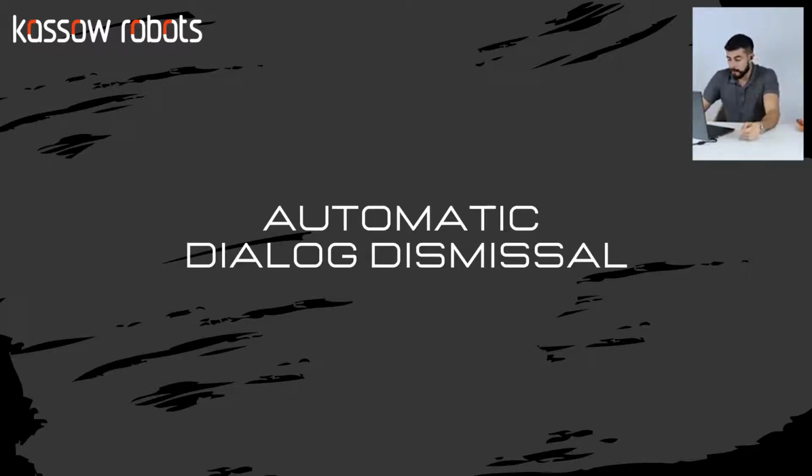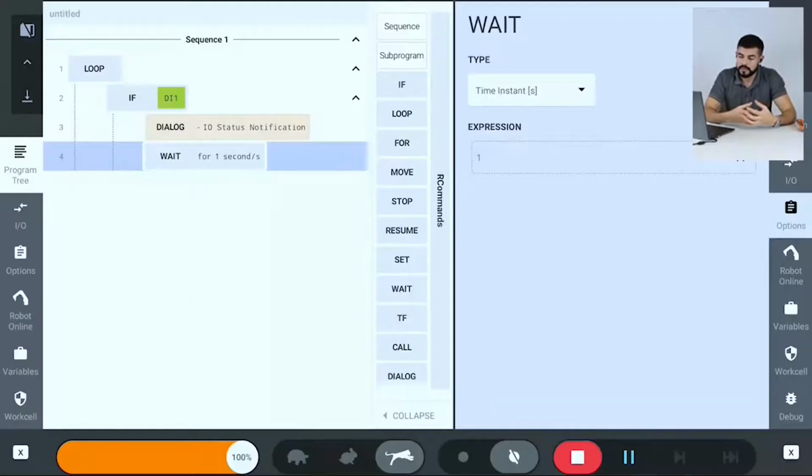Automatic dialog dismissal. It is now possible to dismiss the pop-up automatically. When you're using a dialog, it shows a pop-up and you can interact with the user. But before, you were obliged to wait for the interaction with your user, who needed to dismiss it or click on some button. Now you can easily associate it with a variable, for example an input or output, or any kind of variable change, and you can dismiss this pop-up automatically.